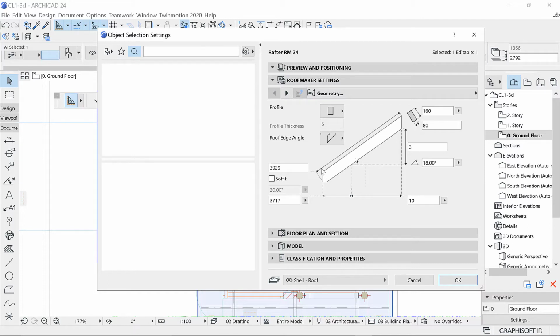If you're taking one sheet of 2 meters, for instance, it will run from this point to maybe somewhere at this point. Then I'm adding on another sheet of 2 meters, and it may come to about 4 meters, because 2 meters plus 2 meters makes 4 meters. But the thing is, you are going to have some overlap. The overlap is very important to prevent leaks when there's wind, especially wind with rain. If you don't have overlap, the roof is going to leak. So obviously you're going to have overlap.